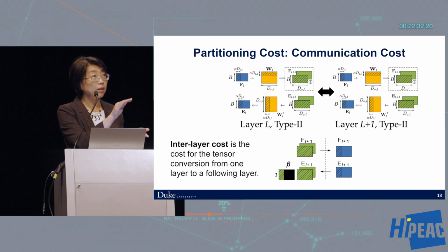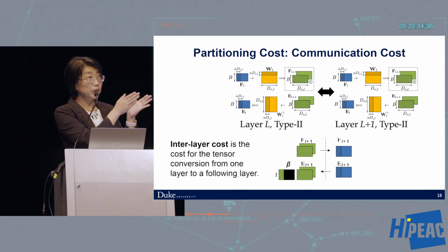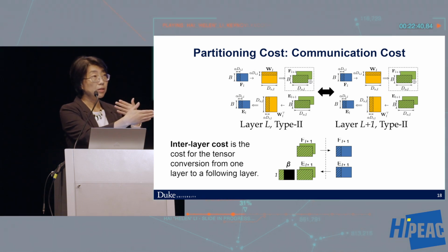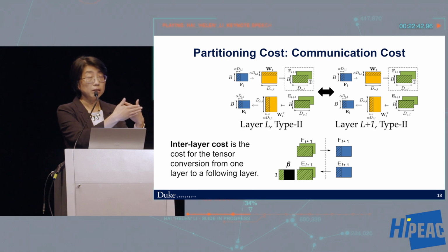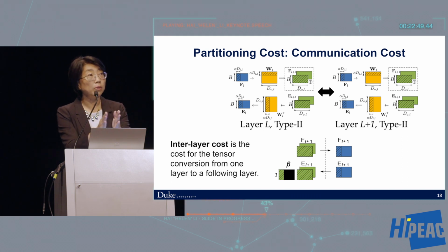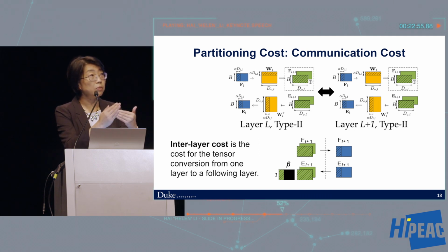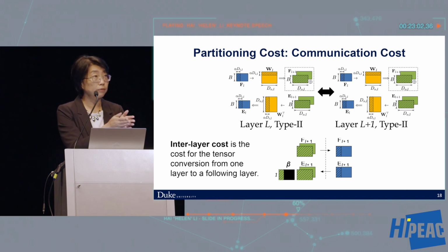On the forward path, as you can see, for the green part, the output feature map F L+1, we have multiple accelerators, and each of them generates partial summations, and we need to add them up. When we pass that to layer L+1, the produced matrices need to be partitioned and distributed into different accelerators, and each accelerator only has a portion of this.